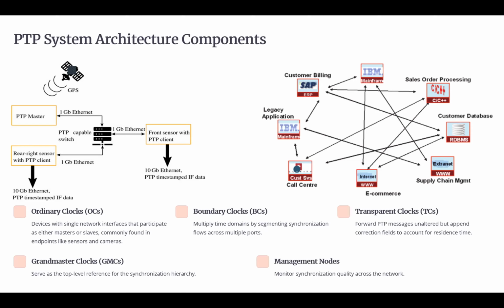And at the same time, when we keep that layer between the grandmaster and all the devices, we reduce the load on the grandmaster. So now the grandmaster has to deal with fewer devices when we're talking about synchronization, which helps a lot when we talk about the delays and the precision of the time. We said that if we have less traffic, we could have more precision in our system.